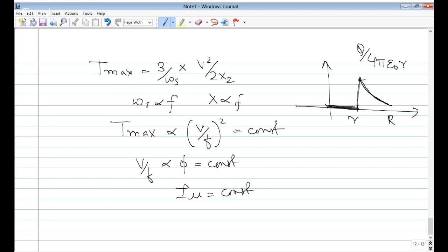Next is again from Rahul Patnaik. When two identical first order systems have been cascaded non-interactively, the unit step response will be... Non-interactively basically means there is no loading effect. That is, there is no current flowing between the first and the second system. So if you are cascading them, then we can directly multiply their transfer functions. So this is the first system. This is the second system. Now, as you can see, there are two poles. Both are real and unequal. If both are real and unequal, that means the system is overdamped. So answer should be A.